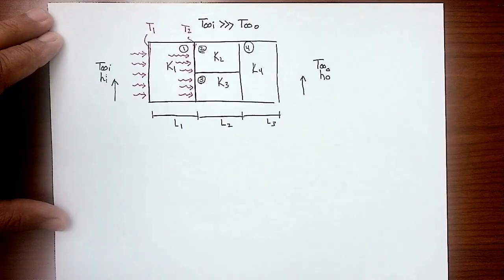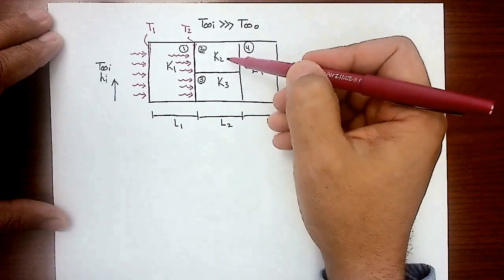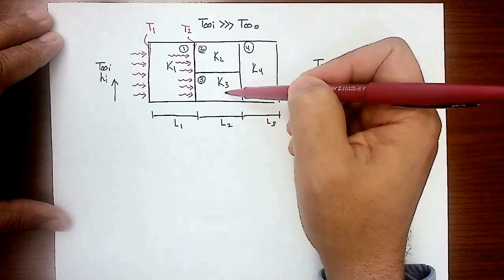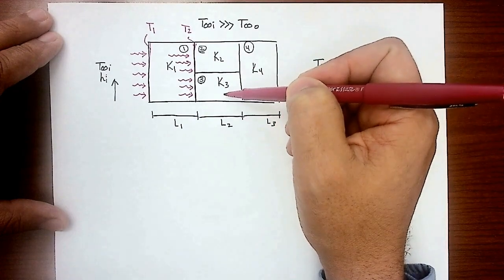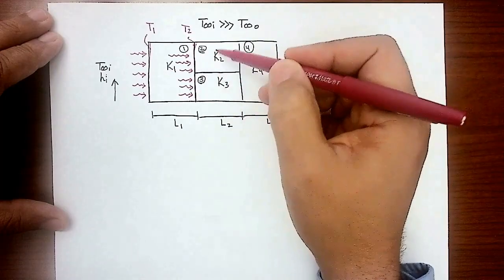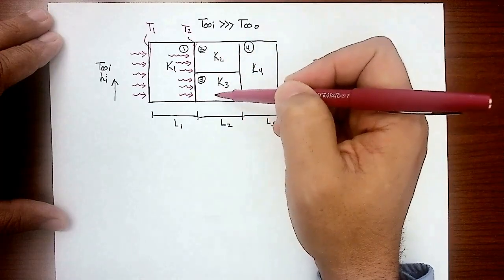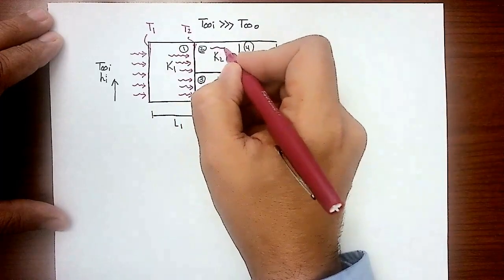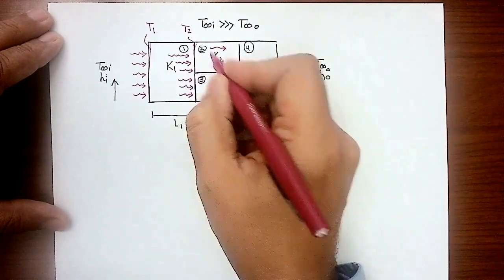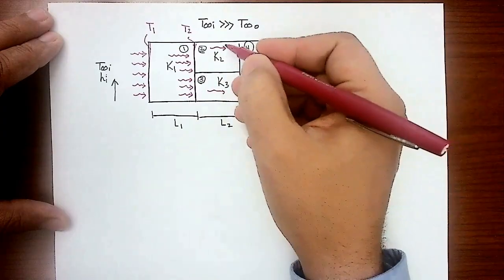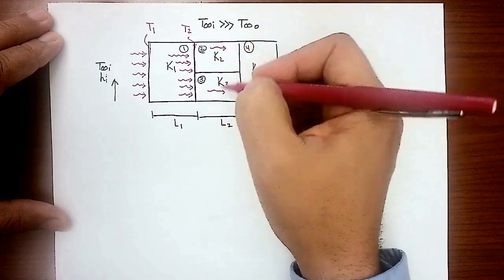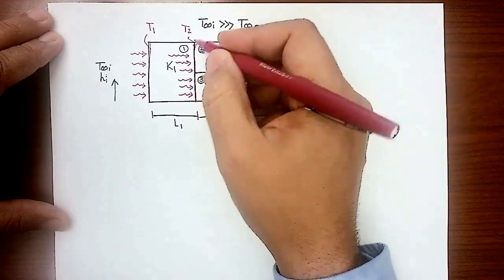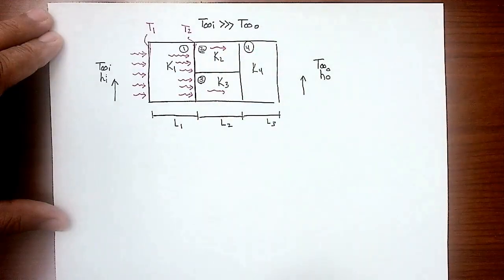Then energy has to split, not equally, but it has to be divided. Why? Because I have a block that's made of copper, and a second block that's made of concrete. It's impossible that energy will split equally between two different materials. One of them has a higher thermal conductivity. So energy will divide partially at the top and partially at the bottom, but still the summation of these two parts should equal the total energy that was actually sitting on that face.